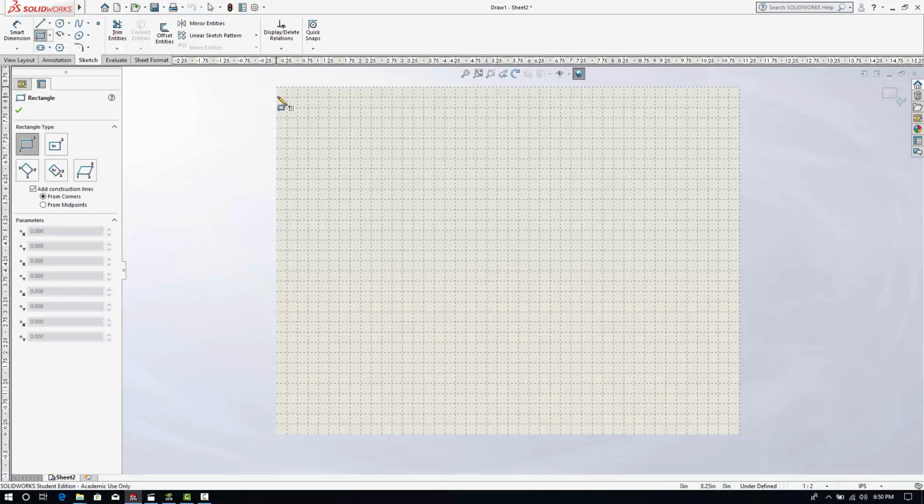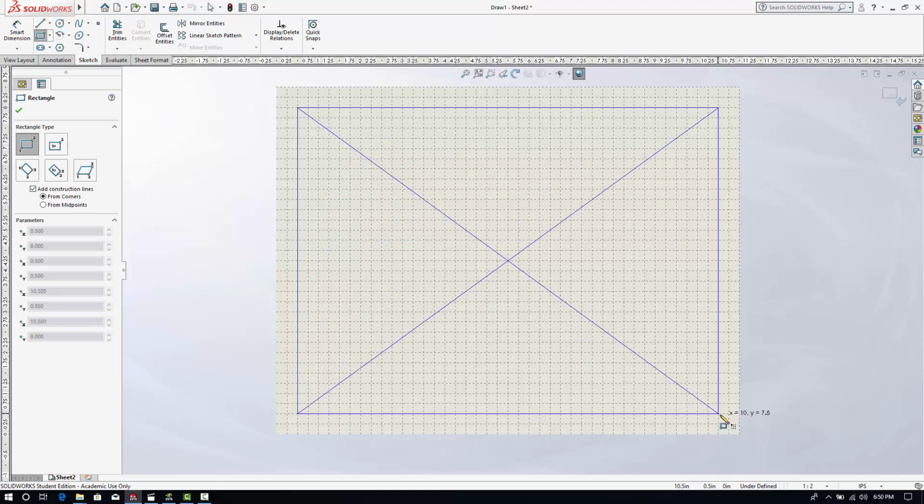And I'm going to start with a corner rectangle. The nice thing about snap is that it actually snaps, so I'm not drawing in space. It's actually going to snap to a point. So I want to make sure it's equal. So let's start the rectangle right here. And I want half an inch of space around, so I'm going to leave 2 squares.